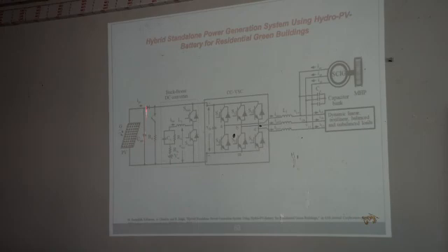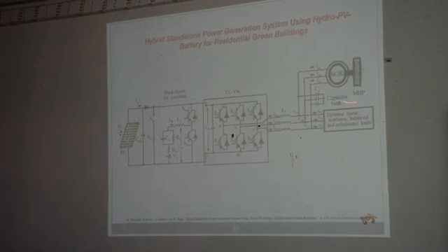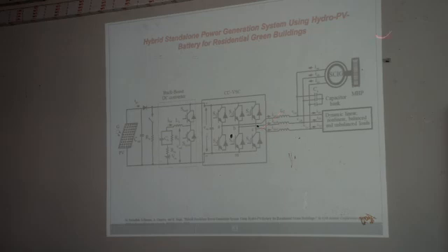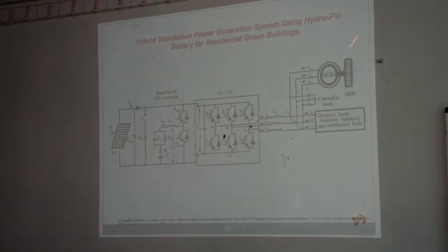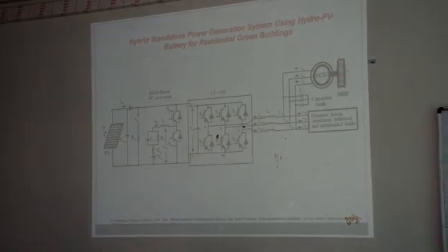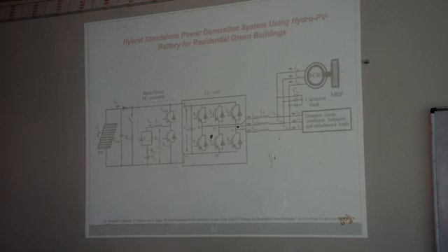So here you have a PV and another case of power generation, which is hydropower. This generator is operating at fixed speed. It's a fixed speed operation. It will take care of voltage and frequency control, and this converter will take care of voltage and frequency control for this local grid, and the DC link is flooded with the PV power also.